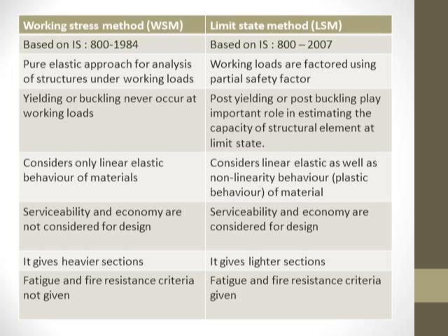The working stress method uses a pure elastic approach for analysis of the structure under the working loads. In the limit state method, the working loads are factored using the partial safety factor, so that on the safer side the loads are made higher.